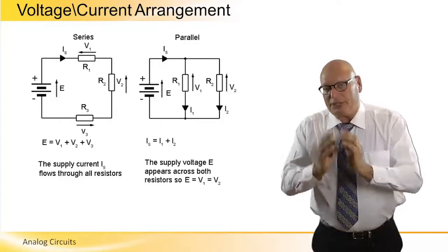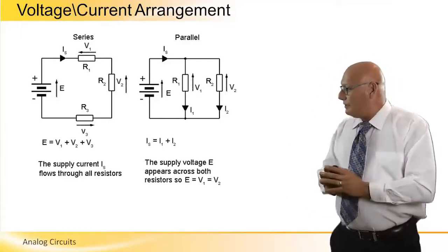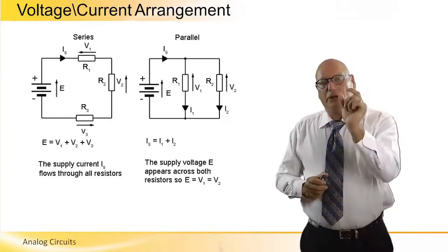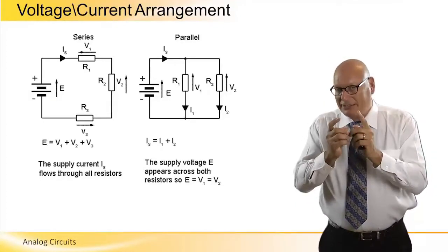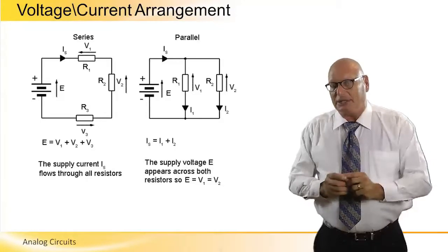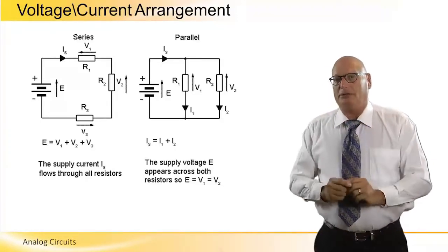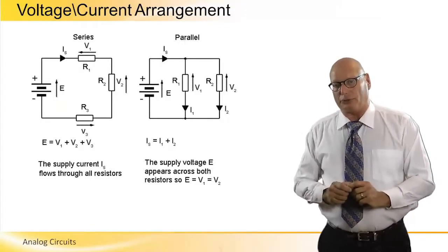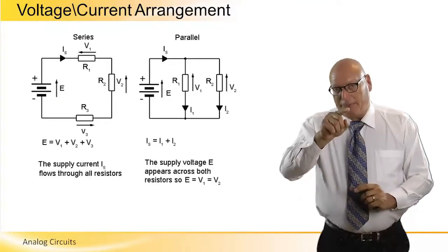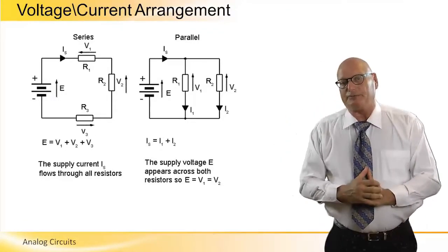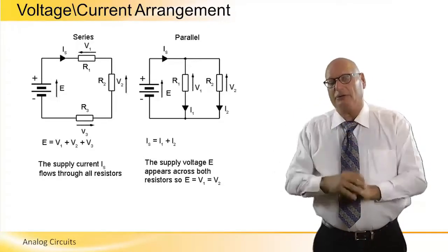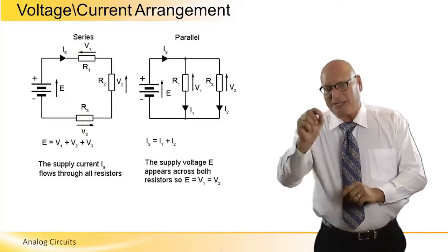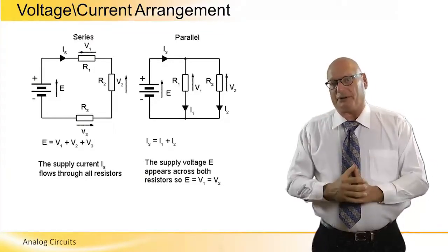So this particular slide demonstrates to us that on each particular resistor, there's a voltage drop. And we can understand from this slide the direction, the polarity of the voltage drop. The plus side of the battery, which is the longer bar, is basically the plus side of V1.